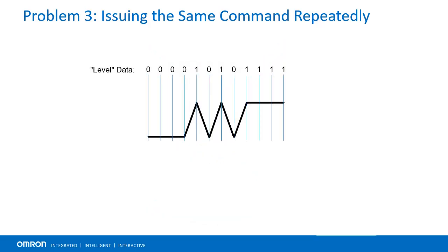Similarly, if the user is making a counter, it would keep counting as long as the signal is high, rather than once each time it goes high. By comparison, in edge-triggered logic, that code won't care if an input is high or low. Instead, it checks if it previously was high, but now is low, or vice versa. The logic will only trigger once as the input goes high, and then nothing else will happen until the input goes low. If a user wants their code to only trigger one time from an input, edge-triggered logic is the easiest way to do so. Instead of manually coding this, buffered I/O has pre-made structures for it.